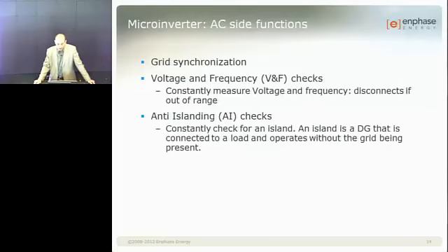On the AC side, well, we need to synchronize to the grid, so we are slave to the grid. Before we turn on, we have to listen to the grid and ask, what phase are you at? Is the voltage okay? And we need to lock up to that, and before we're ready to inject current, we have to be exactly in phase and sure that the grid is okay.